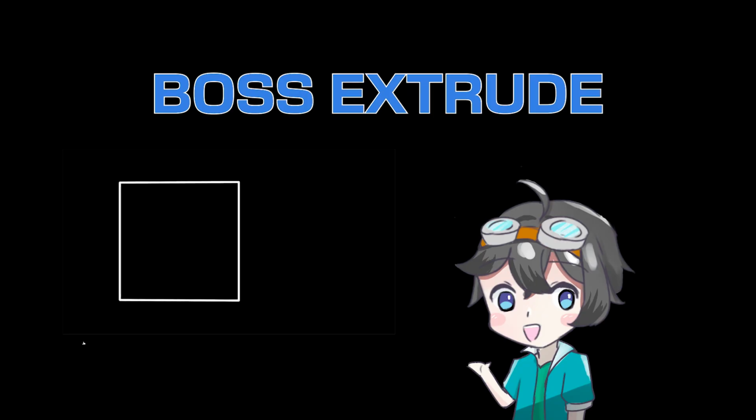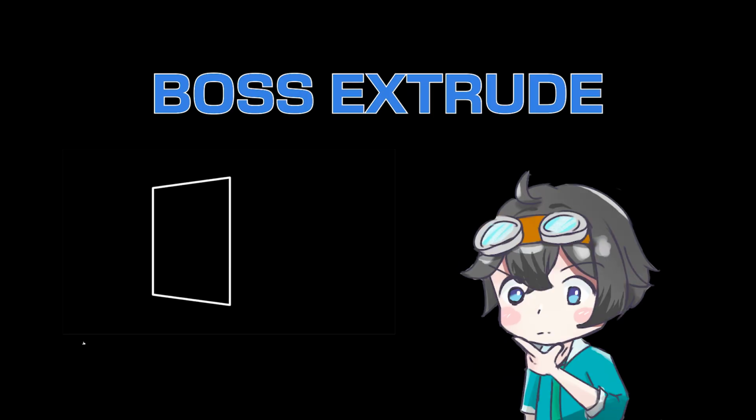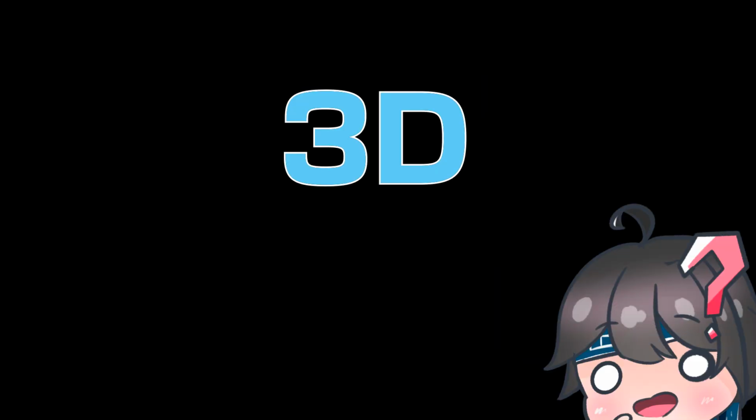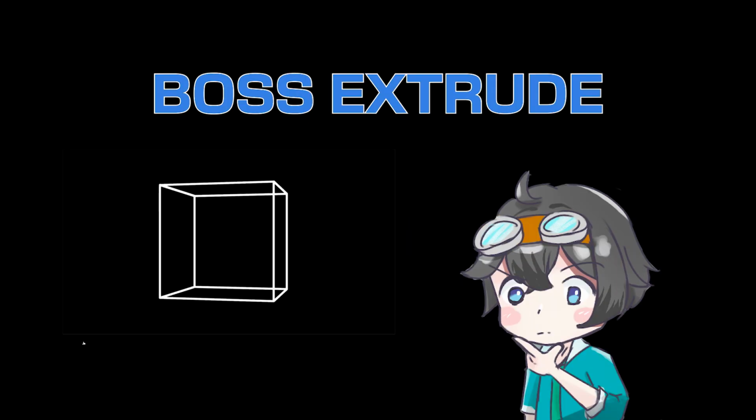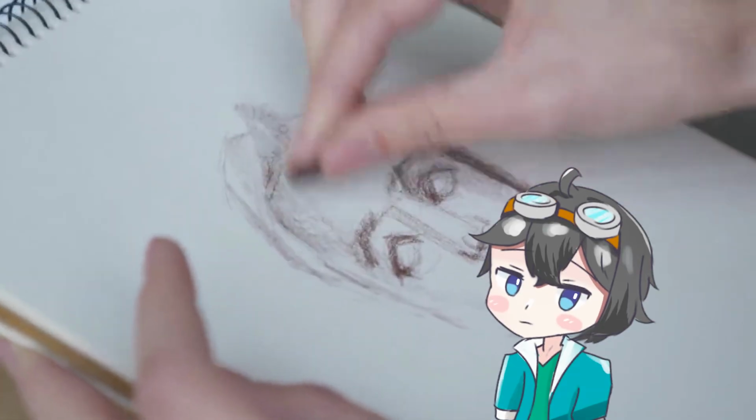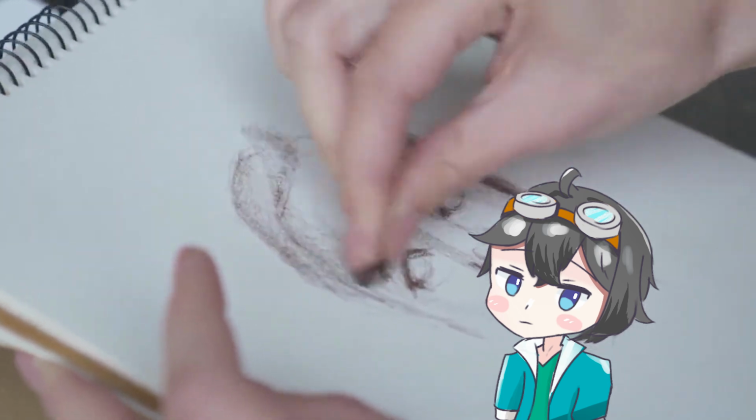Boss extrude is one of the most commonly used features in SolidWorks. It converts a 2D sketch into a 3D geometric shape by adding depth to the sketch itself. To use the Extrude Boss Base tool, you first need to create or enter a sketch.